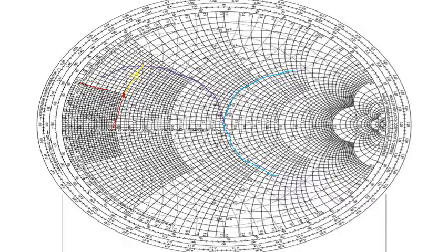So how do I measure the value? You can see. Now looking at this arrow, how do we find out? You have moved along the solid circle. In what movement does this yellow color show? You have moved up. So what will you make? You will always make an inductor. Along which circle did you move? You moved along the solid circle in the upward direction. Solid circle, series connection. Upward direction, inductor. The first diagram which you are going to make is going to be about an inductor. It's going to be a series inductor. Am I clear? I repeat. We moved from the ZL point.